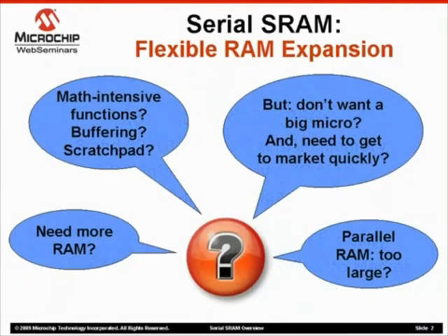So is RAM expansion using serial SRAM an interesting proposition for your designs? Here are some questions to think about while we go through the presentation. First, do you simply need more RAM for your application? Second, are you performing RAM-intensive functions like math algorithms, data buffering, or audio-video applications that need large amounts of temporary storage? One solution to these problems is to buy a larger micro with more RAM, but that can result in a more expensive design and a longer time to market.